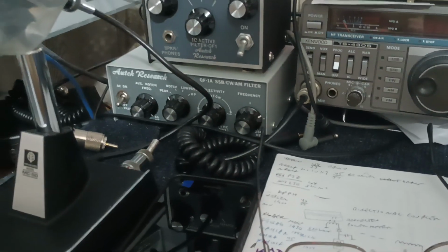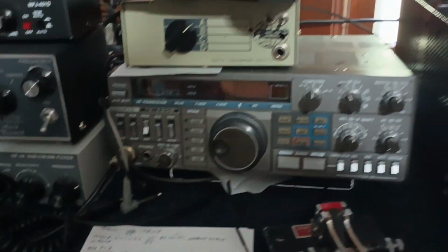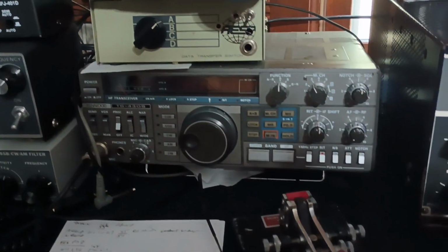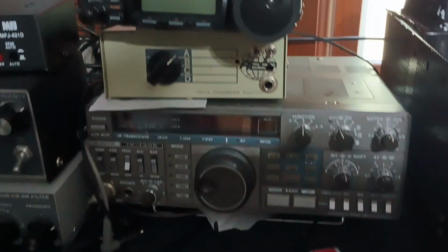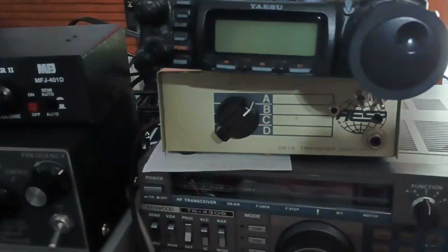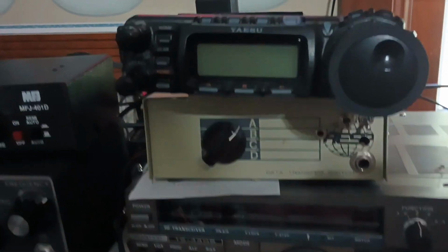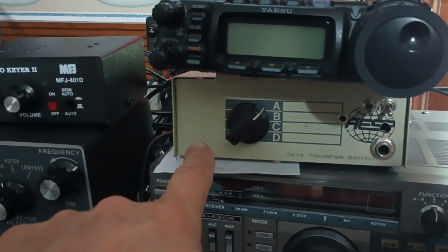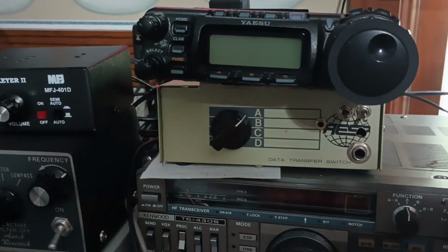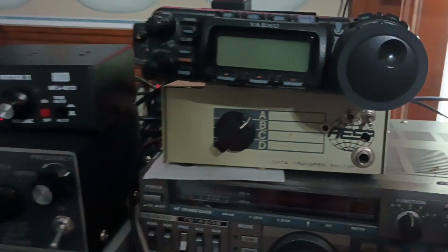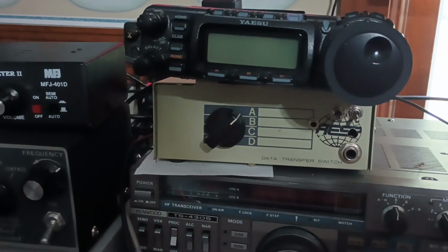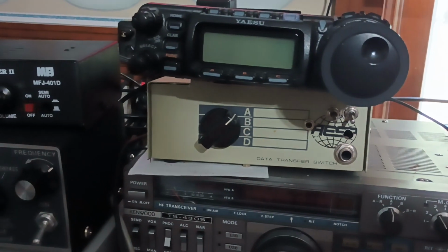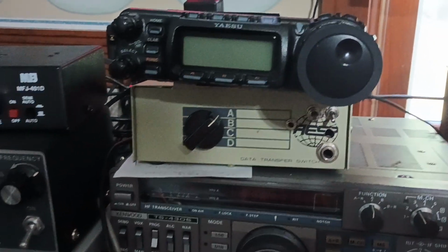The peak-to-peak voltages coming out of these rigs to the speaker or headphones is somewhere around a max of a couple of volts. On the AC857, I designed the CW keying adapter to take the side tone, strip the tone off, for a speaker out voltage range of 0.1 up to 2.6 volts peak to peak.